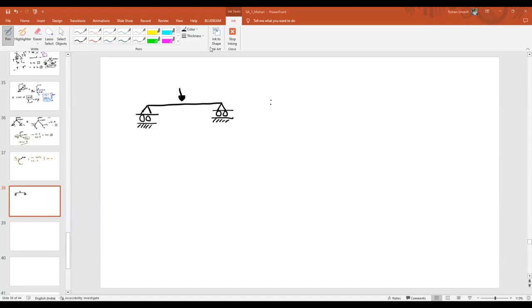Can you just explain why it's no? It's not like our regular class program where I'm going to scold you, or I don't have any of your internal marks. It is determinate only. Why is it determinate? Because there are roller supports, the beam can move along the horizontal direction, but look at the type of force given in this problem.